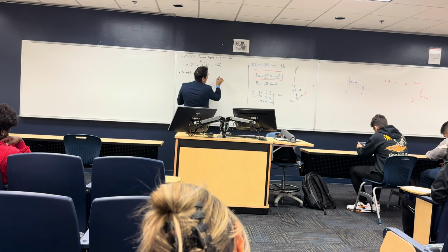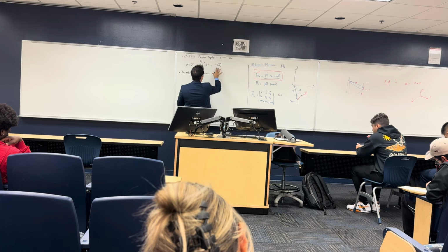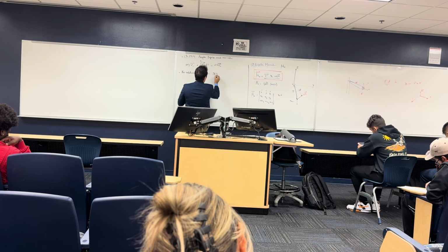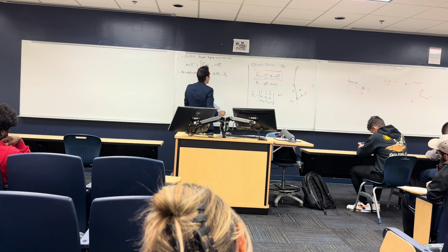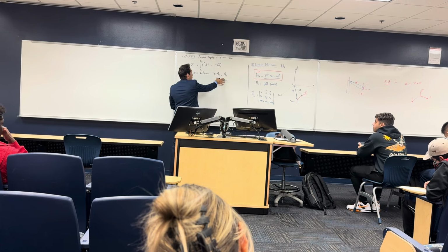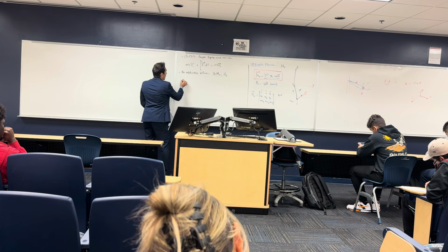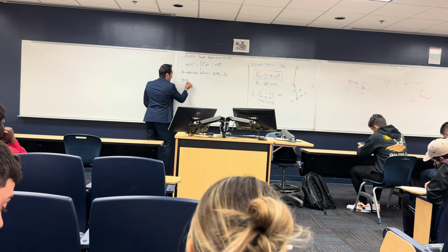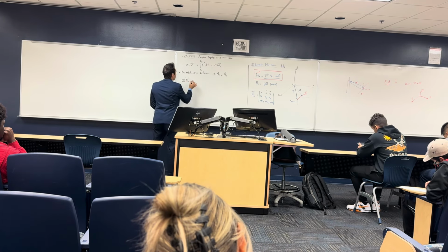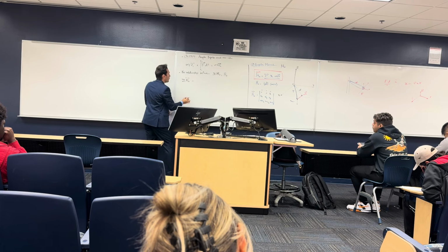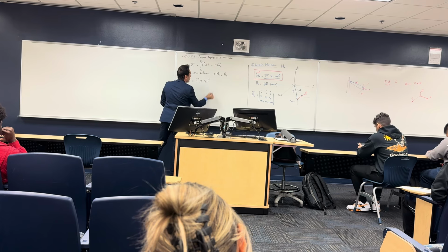Let's write the moment of forces, which is the sum of the moment of the forces about point O, and the momentum HO. I want to find the relationship between these two quantities. How can I find this? Okay, let's get back to the basics. The moment about any point O is a vector product, not a scalar product, equal to the R vector multiplied by the sum of the forces on this point.